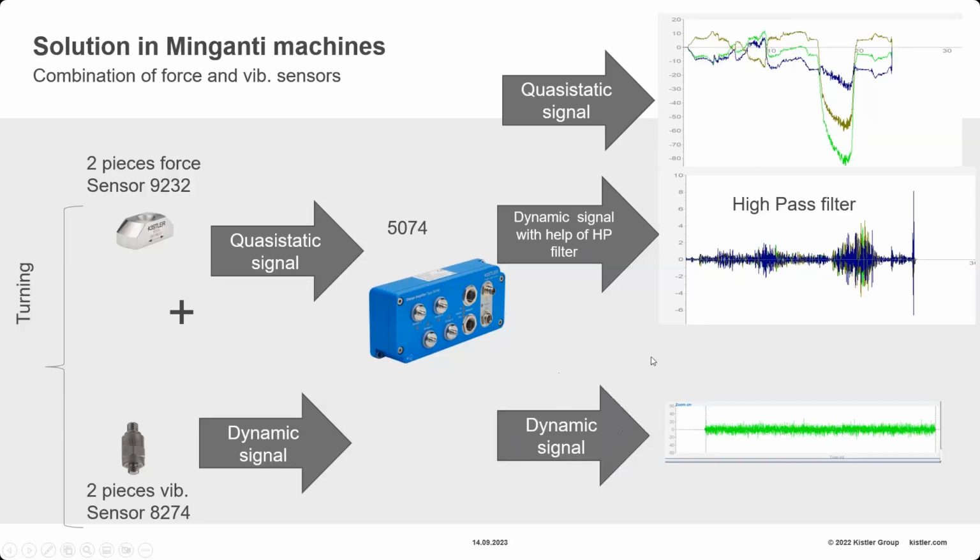So in these machines now, we are utilizing these two for tool breakage detection, tool wear detection, and also as crash safety, right? Sometimes the wrong programs are loaded, or operators make some errors, and then we do not want the machine to crash into other machine parts or the workpiece, and destroy the machine itself or the part.